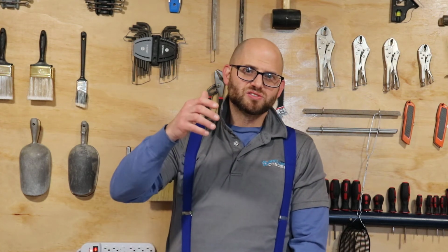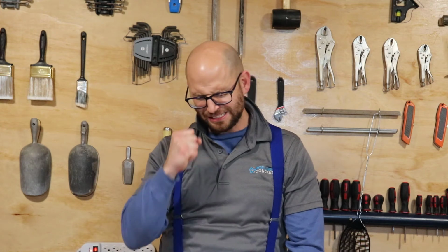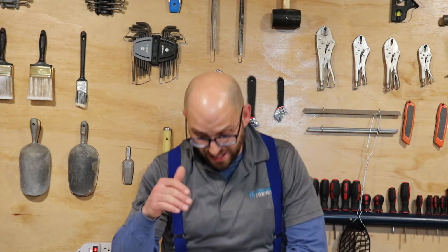It's just too sticky, the viscosity of it changes, the rheology of it changes, so it's not practical, and 10.92% is so gosh darn expensive that it's not a viable, scalable solution for the back of the ready-mix truck. So despite the fact that, hey, bookcrete, labcrete, it looks awesome, realcrete, it wouldn't work. And that's why we don't see this concept, this 45 to 47 nanometer at 10.92%, which I believe is around 20 or 30 gallons, so it's even difficult to get into the back of the truck per cubic yard.